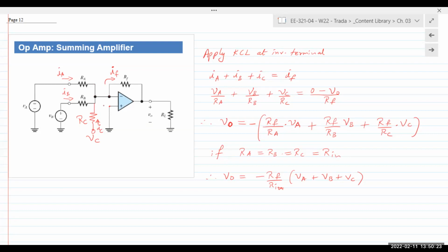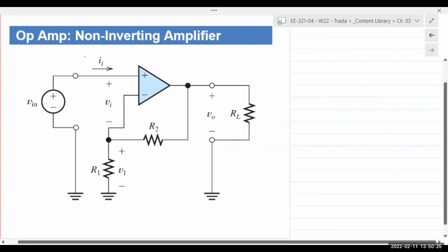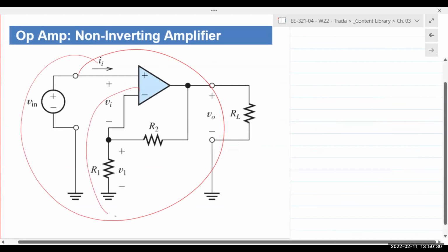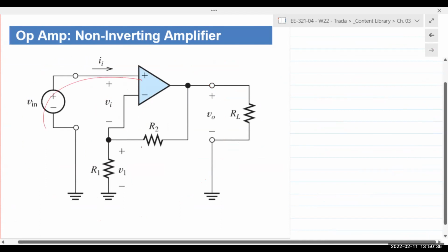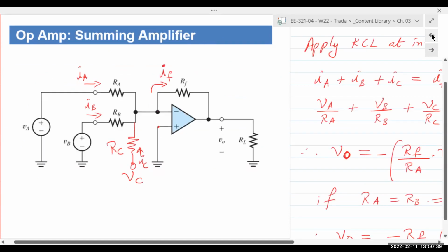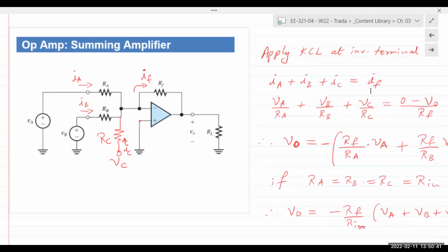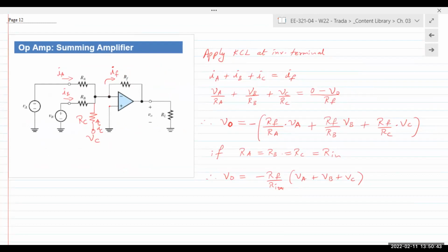That would come in this non-inverting amplifier, where we are actually grounding the inverting terminal and giving the input to the non-inverting terminal. Actually, not really. I'll redraw that circuit. So the answer is no, you can't actually connect it to ground. If you connect it to ground, then current has a pathway to actually just flow through there, and the feedback path would just be useless in that sense.